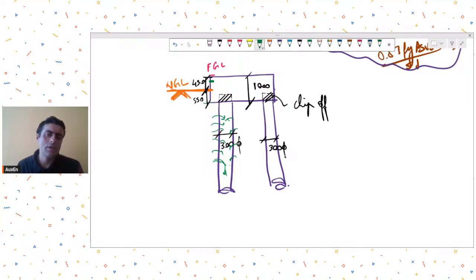And when we are filling it with concrete, those deleterious materials, because they are light, rise up to the top surface. Also, the bleeding water due to segregation also rises up to the top surface. So generally this top surface is the weaker zone in your pile length.